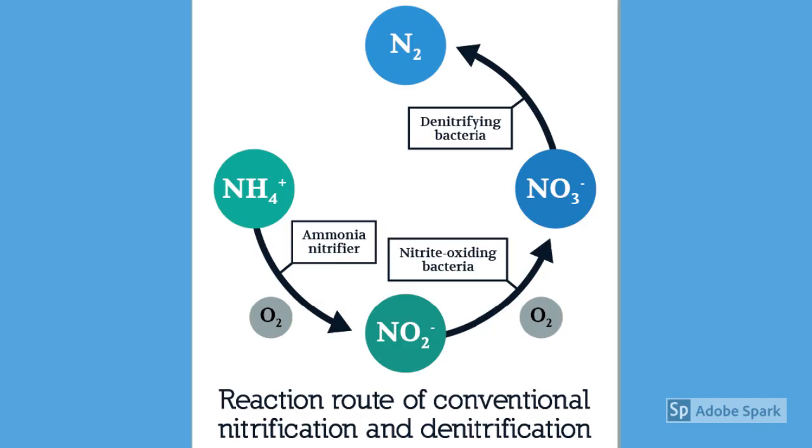It is from here that heterotrophic bacteria, grown under the anoxic conditions present in the tank, can make use of the nitrate created by bacteria under the aerobic conditions. The process performed here is called denitrification and involves the conversion of nitrate to nitrogen gas, which is then released harmlessly to the atmosphere.